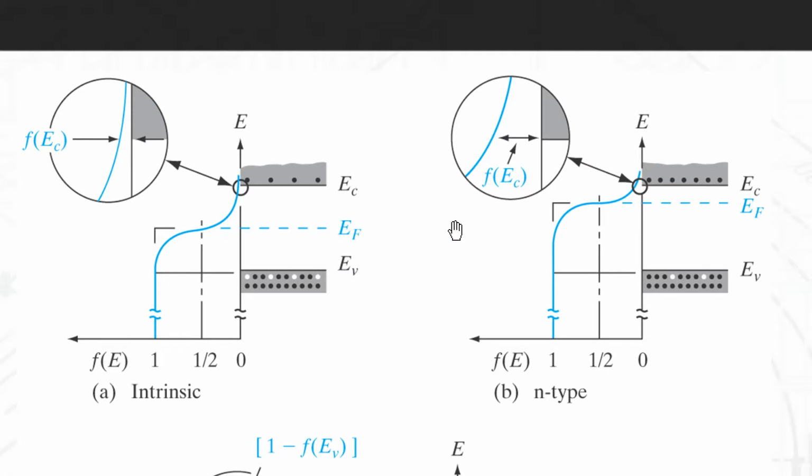All right. So as a result, you have more electrons in the conduction band, and conversely, your Fermi level is farther away from EV. Before there was a probability that was very close to 1, and here the probability is even closer to 1. So there's very few empty states. These states end up being mostly full, even more so than before. There are still some holes there, but very few and far between.